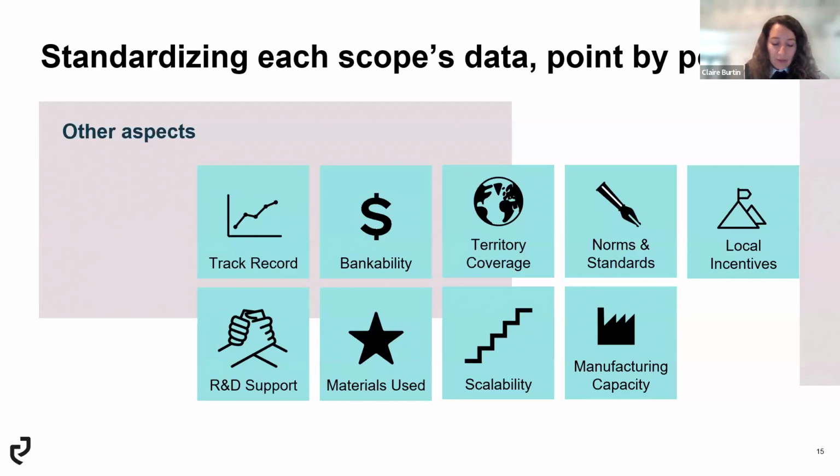So we realized that the standards are not well defined today in the hydrogen industry for calculating the hydrogen flow and the hydrogen efficiency. Western European, American, Canadian electrolyzer manufacturers are calculating the hydrogen flow by measuring the volume of hydrogen out of the electrolyzers. And that's how efficiency and capacity of electrolyzers are mostly calculated for those Western vendors.